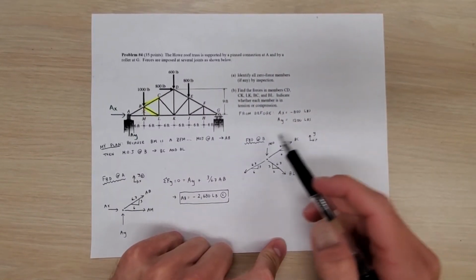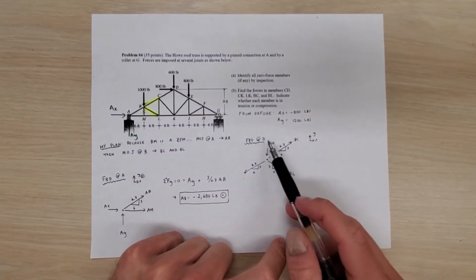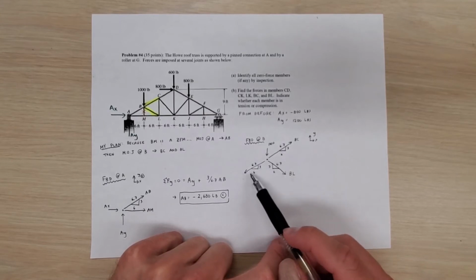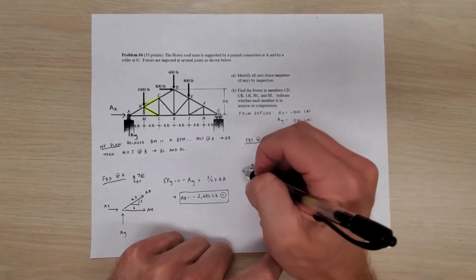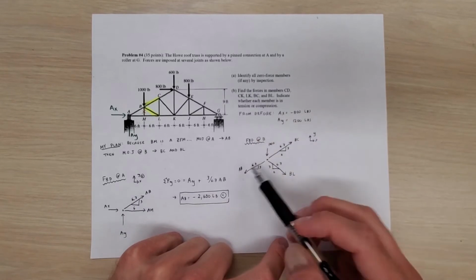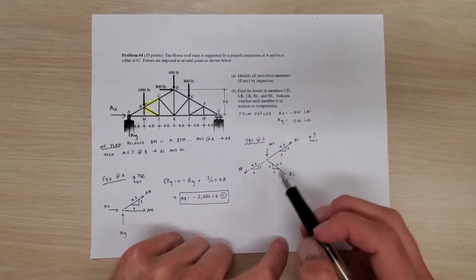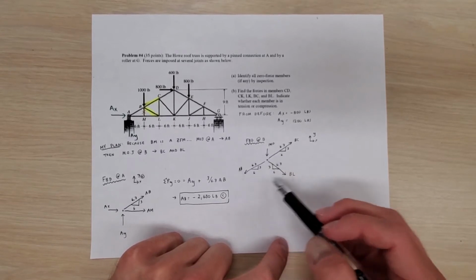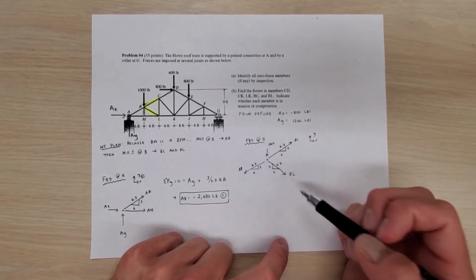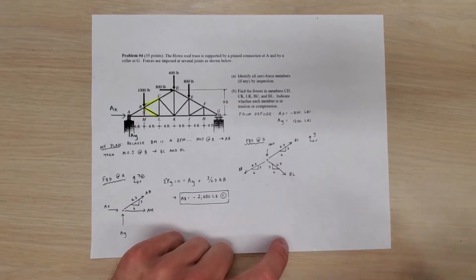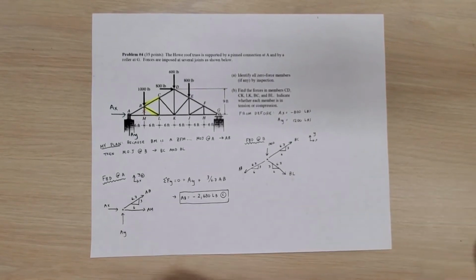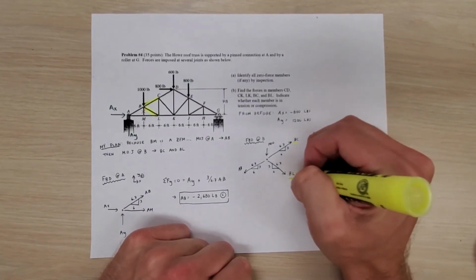Now I've got the free body diagram of point B. What you can see is I've got the 1,000-pound force coming down on the truss. I've got member AB with its force here. I'm assuming it's in tension, even though I know it's in compression, but that'll work out. I've got BC and I've got BL here, and the geometry of all of these is the same. It's a 3, 6 by 6.7 triangle. So the two unknowns I have right now are BC and BL.